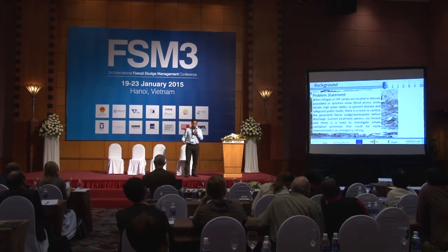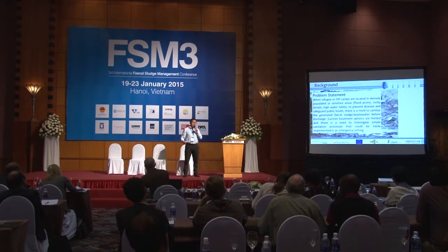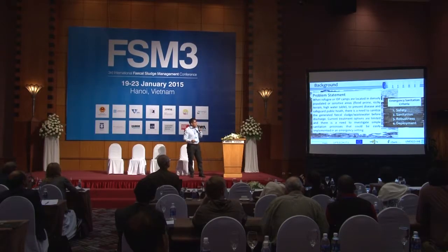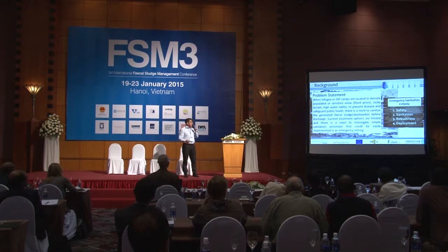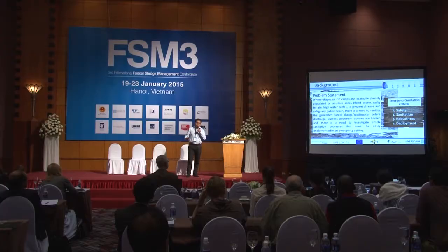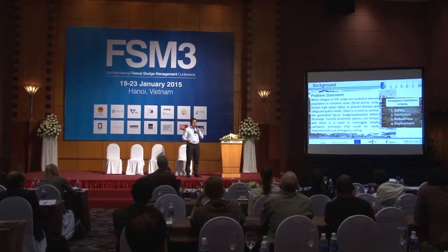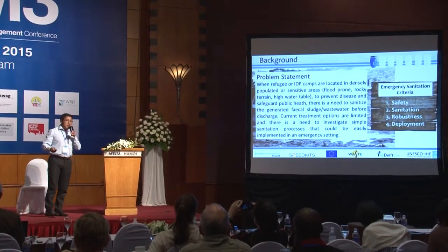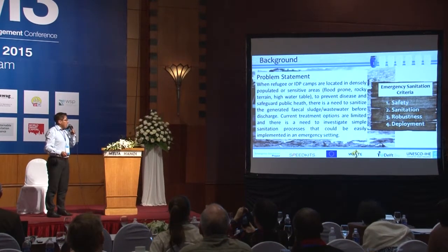These treatment methods were investigated based on looking for some options to treat fecal sludge in emergencies. That's why we have 4 criteria, which is very important for us at the time to decide which methods could be used. The first one is it should be safe. The sanitization was a key factor. Also, the treatment should be robust enough because there are different types of emergencies and different types of fecal sludge. And the deployment should be easy to transport.